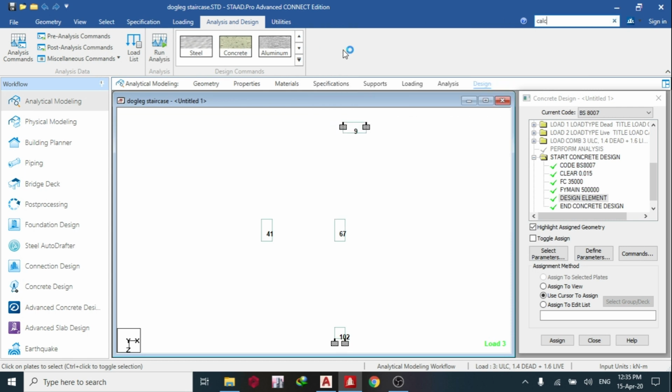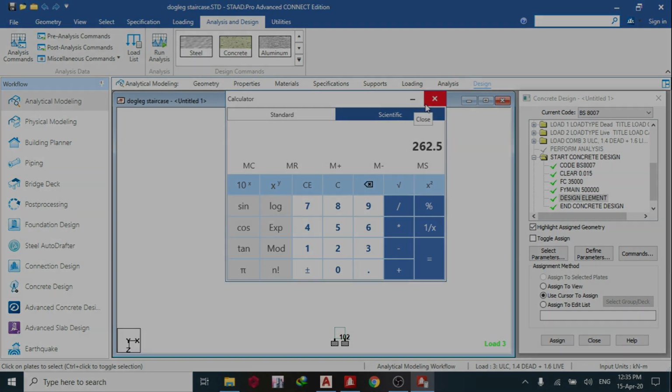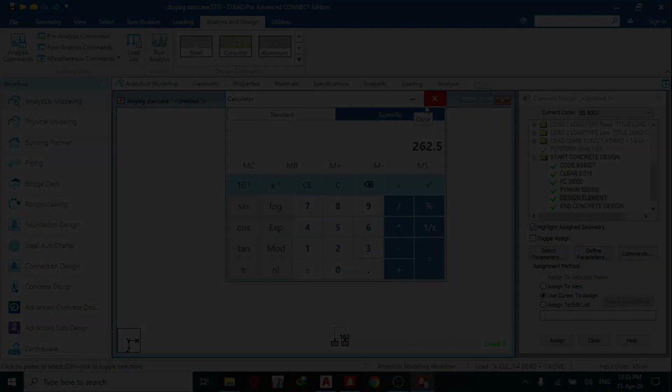Calculator. So to get your distribution bar, it is 0.15 times the thickness of your concrete, 175. So once you use this, 0.15 times 175 times 1000 divided by 100. Okay, so we have 262. So we can use Y10 at 300 center to center, or Y10 at 250 center to center. So you check your steel table. So another way of checking.